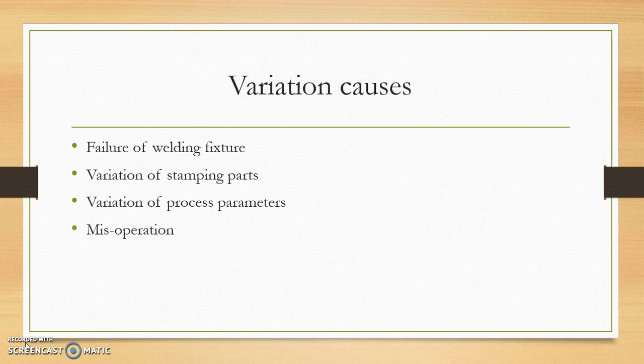Coming to variation of stamping parts. Although having been precisely controlled, stamping parts inevitably have dimensional variation because of the uneven material characteristics of sheet metal, the varying of the stamping die, and the variation of the control parameters of the press machine. Usually, variation patterns display apparent differences between batches.